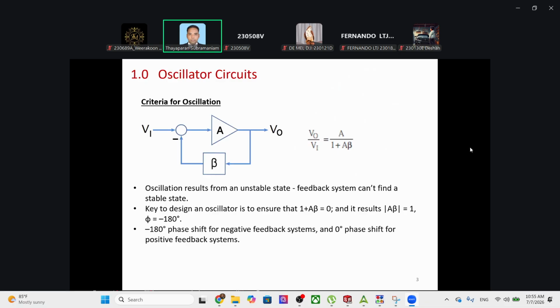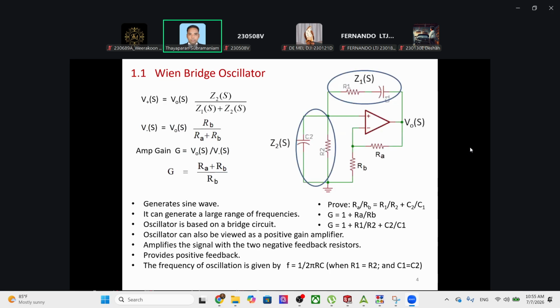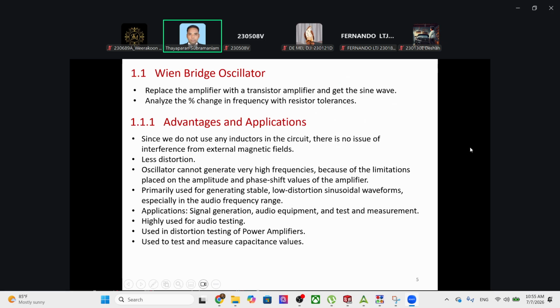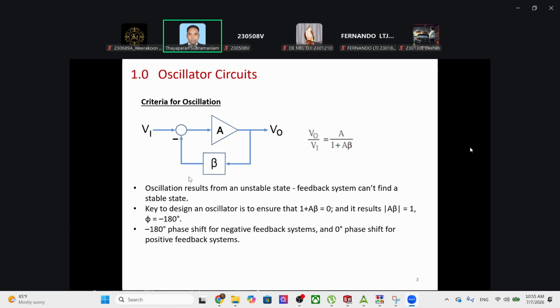complex. Complex means what? When you have capacitors and resistance, there will be a phase shift. So we have to observe the phase shift, and if it goes beyond 180 degrees, then what happens? The phase shift introduces another minus sign, right? That becomes a negative feedback system.